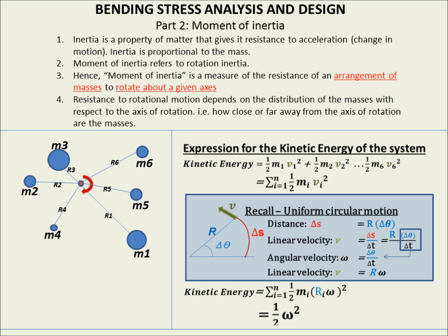Their linear velocities will change depending on how far away or close they are to the axis of rotation. But their angular velocity is the same, so that's a constant. Okay, then we're going to replace the summation with an integral sign and go r squared dm, right? We've taken out the constants to one side, and we've rewritten the summation sign as an integral sign.